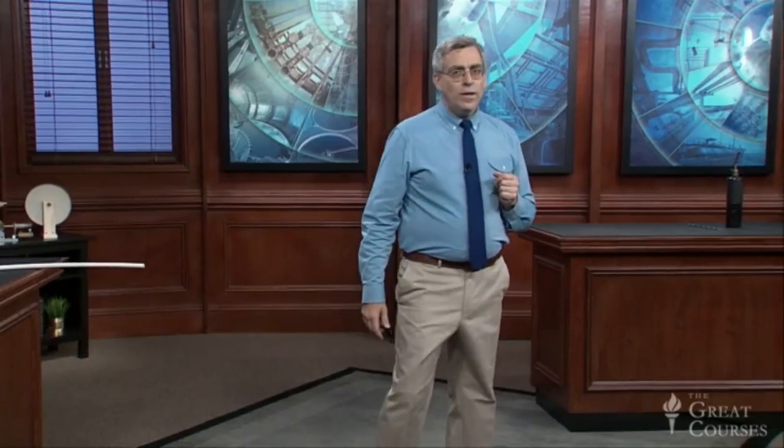Each is really just a copper coil with a fan blowing across it. Thus, in a combined heat pump air conditioner, each coil can be used as either a condenser or an evaporator. And the only mechanical action required to switch between cooling and heating is to reverse the direction of the refrigerant flow. This is accomplished quite elegantly with the aid of a few cleverly designed valves.